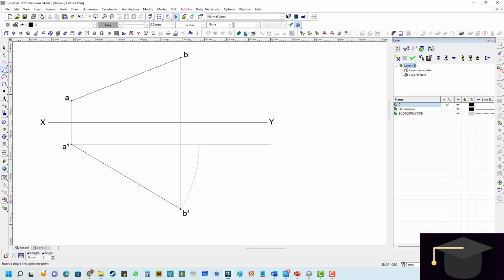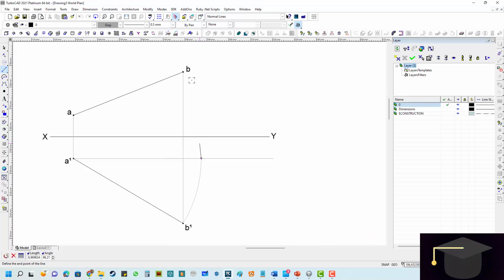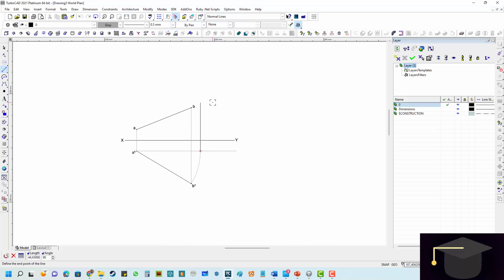So I'm going to select my line tool, make sure that it's on gray, and then at that intersection press I on the keyboard and then I click and hold shift and drag that line out vertically like that, indefinite in length for the time being. We'll do the cleanup just now.